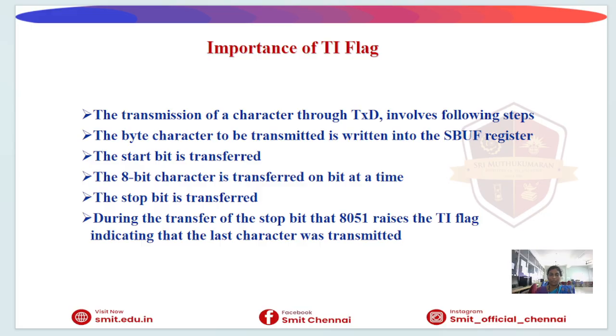Next, what is the importance of the TI flag? When a character is transmitted, the following operations take place. First, the data byte is loaded into the SBUF register. Then the start bit is transmitted. After that, the 8-bit data is transmitted one bit at a time. Finally, the stop bit is sent.